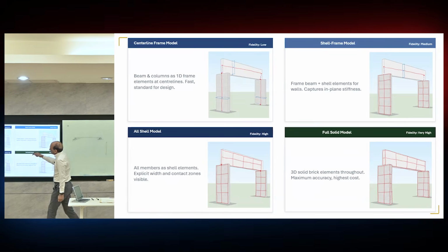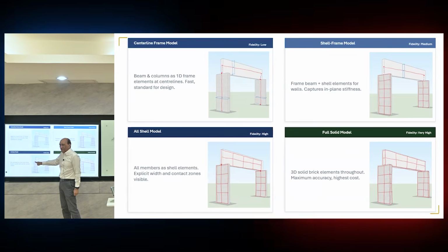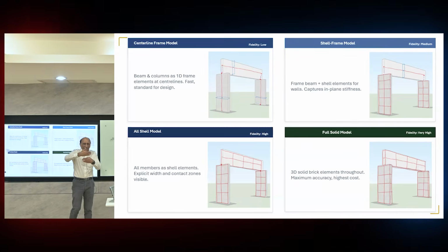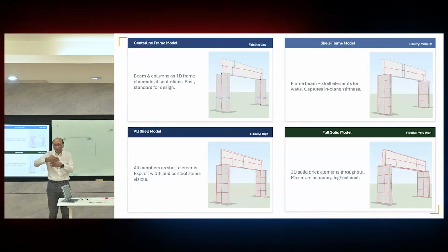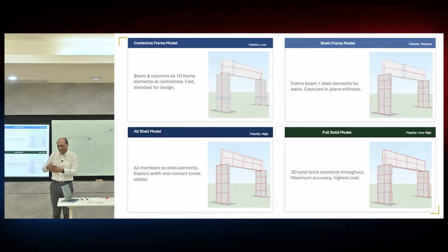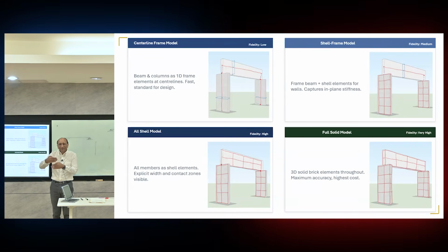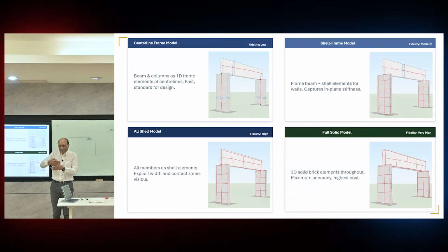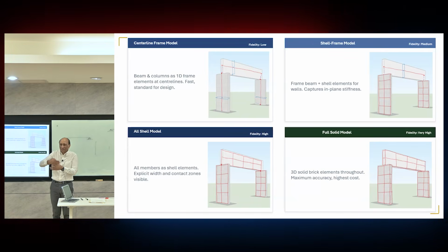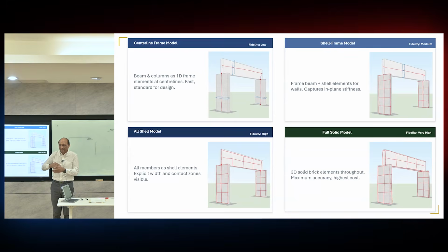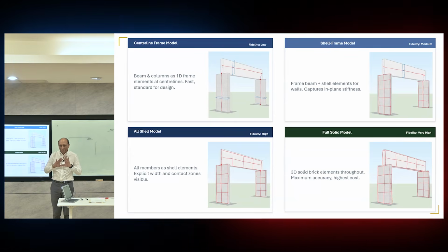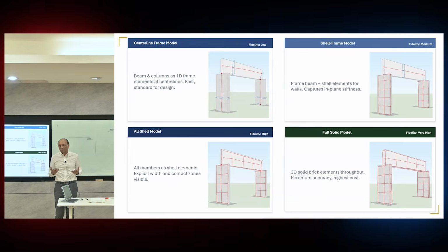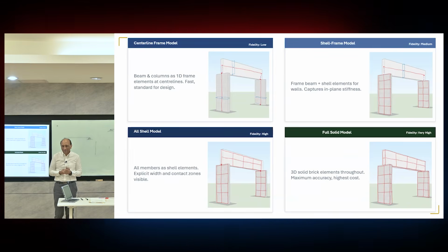Second problem is that this connection between them is actually rigid, but your beam is just resting on it, not connected to it. But here you connect it. How can you have a finite element where the connection is just resting there? It can lift off, it can slide, it can rotate this way. So you can see that even though you get a full shell model, looks very nice, but you still haven't solved the problem of the basic connection.